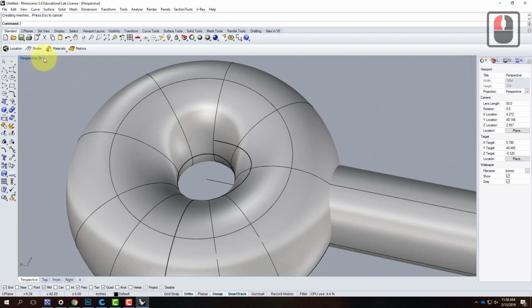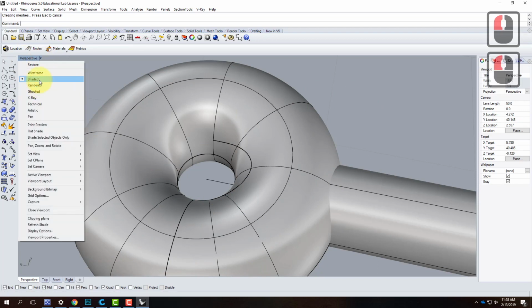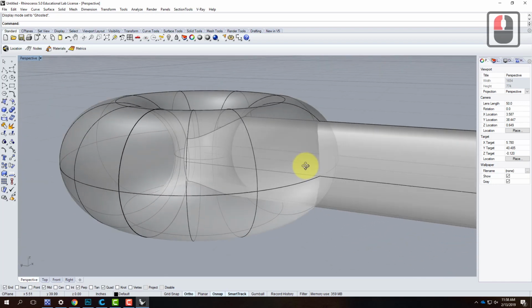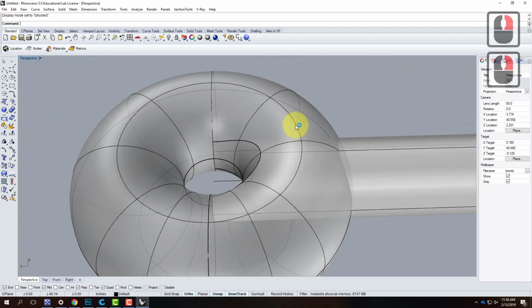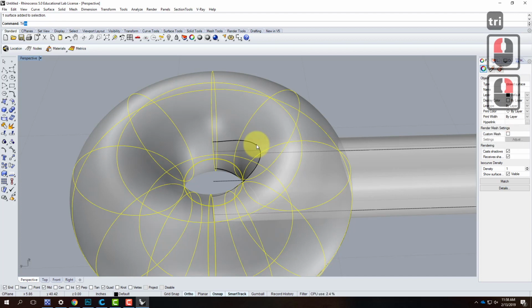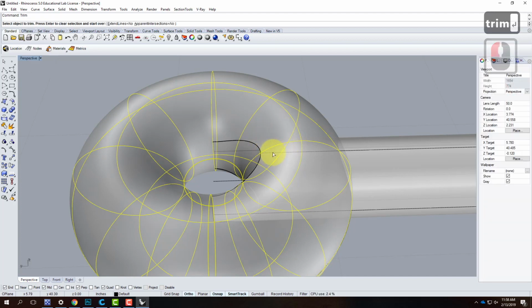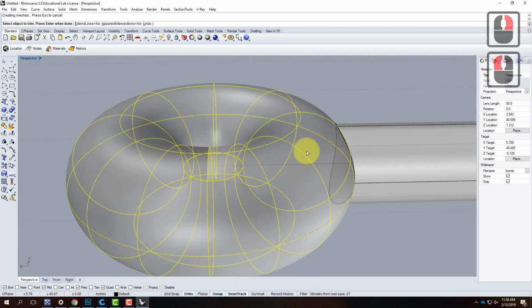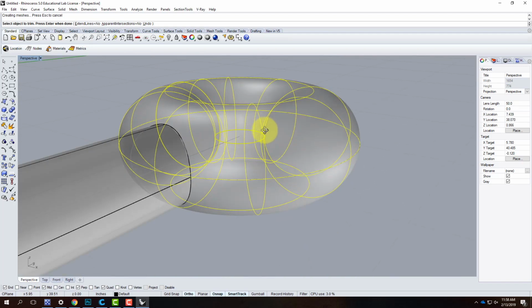This is where using one of your different views can make a difference. So we've worked primarily in wireframe and shaded mode in this class. We've touched rendered a little bit. But down here we have a couple other ones. We have ghosted and X-ray. Ghosted is particularly good for this purpose. So when you have a ghosted view, we can see through our objects, and I can say, oh yeah, there's that piece that's kind of intersecting. I can select the torus, type trim, and I can come in here and actually select the surface inside. And because it's ghosted, it's allowing me to see through and also pick that object. If I was in shaded mode, it wouldn't pick that object. It would pick the object on top. So the ghosted mode can be particularly useful for that.